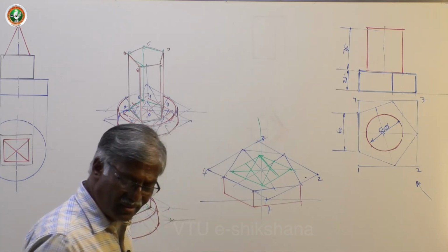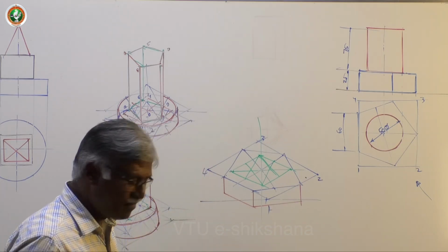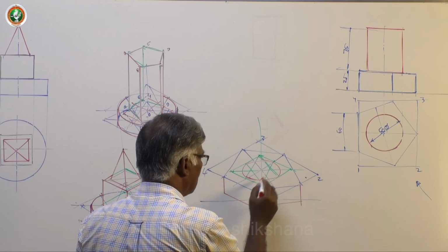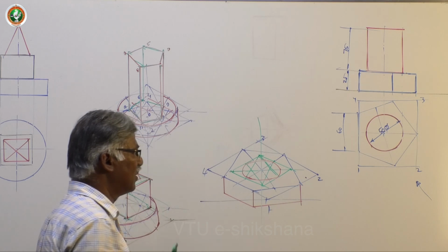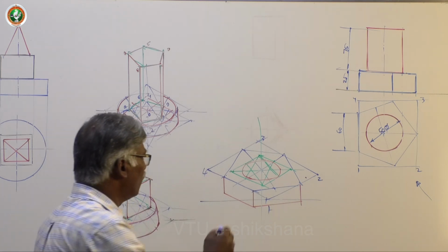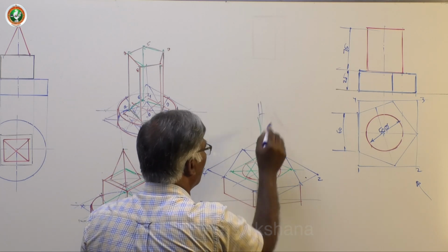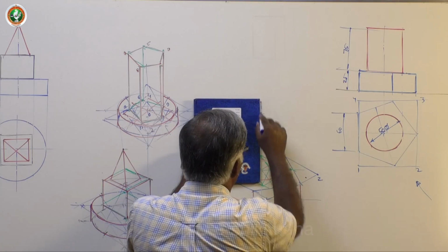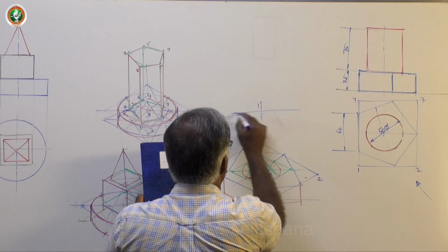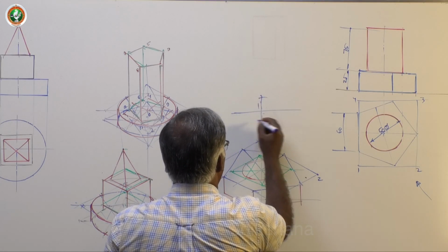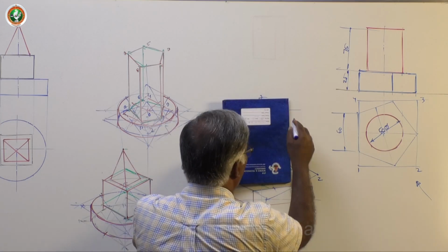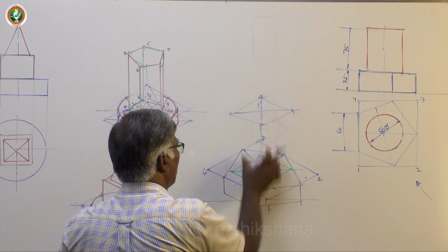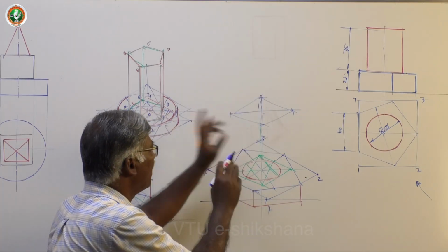Go for the ellipse, you draw this big segment and smaller segments. That's all you have to do. Manually, you have to go up by the given height, 75. Keep the axis, 75, plus mark. Same procedure, 25, 25. Take total and mark. Otherwise, you can just fix this and then project it up. Not necessary. Independently, you can do it easier.